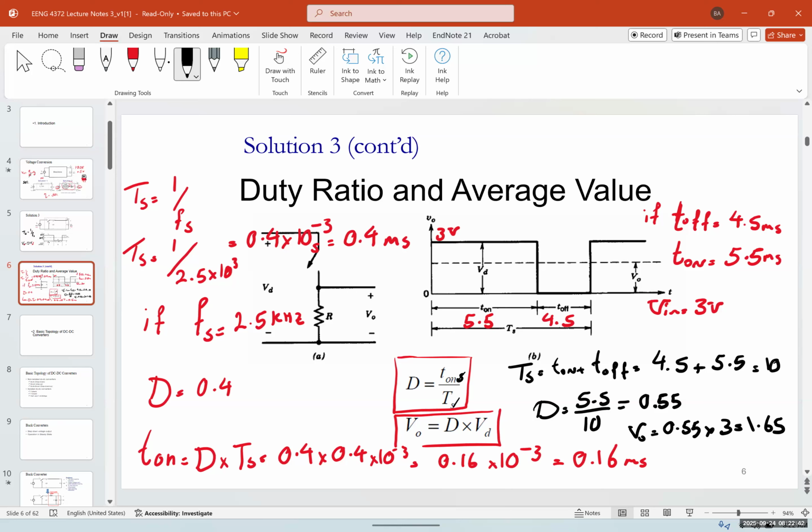Okay. One thing that I wanted to add is that what we just calculated gives us the average voltage. But what we see in the output is a pulsating DC. We know the average is over there, but if you take a voltmeter, or an oscilloscope with a very high frequency response, and put it on R, you can see the pulsating DC. So we need to add different components to make it smooth, so you can have a smooth output voltage.